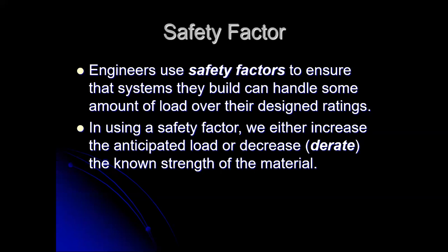Maybe we design it for twice the load, a 100% increase, or doubling, a safety factor of 2. So we design it for 20,000 pounds, but we tell everyone it's only rated for 10,000 pounds. We either do that or we derate the materials by the same factor.